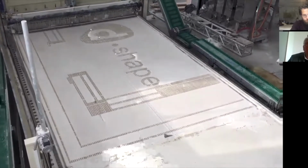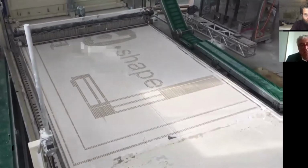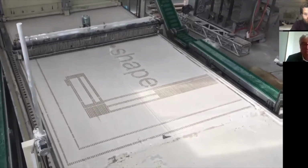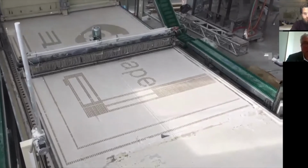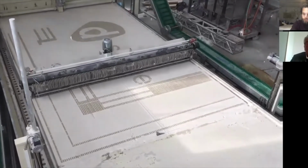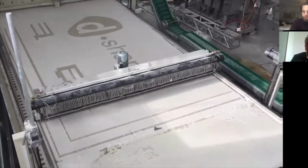So one layer takes about 6 minutes to print, one layer, 1 centimeter thick, of a building 10 by 10 meters on a side. 6 minutes per centimeter.